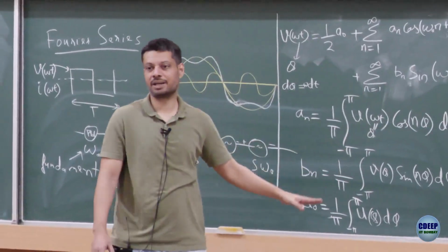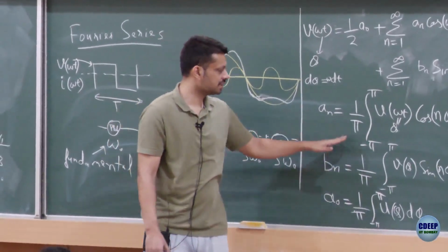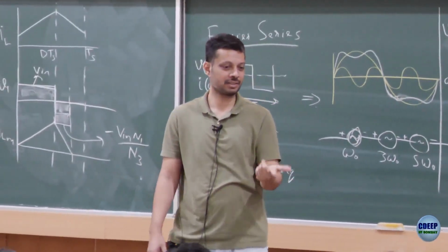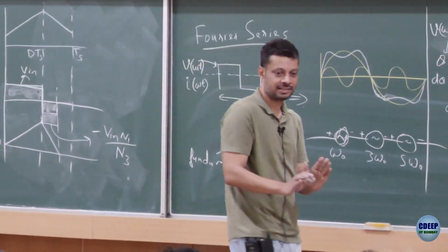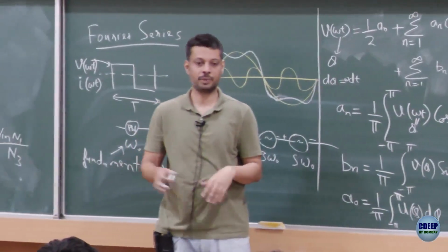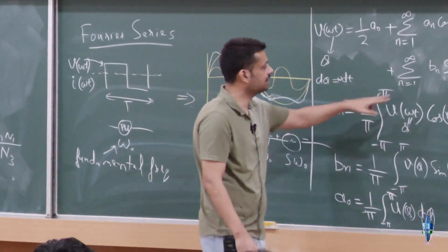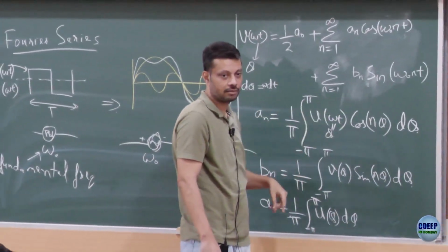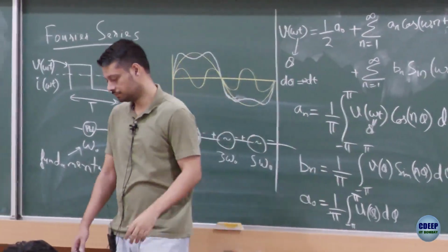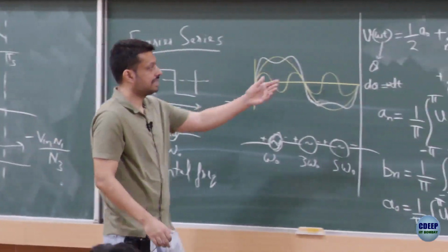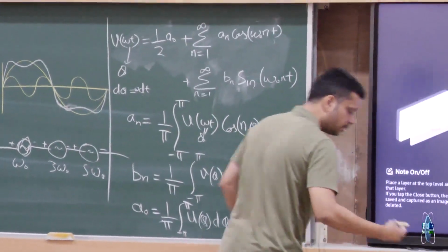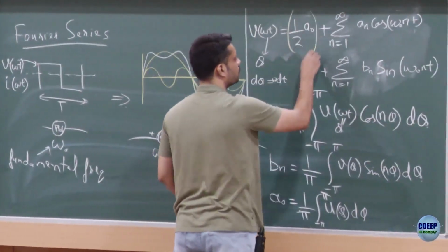That's the reason we are writing it down again, because I know there are different coefficients, there are different limits. The minus infinity to plus infinity you are talking about is the Fourier transform, not the Fourier series. For Fourier series we only talk about periodic signals, so we only integrate from either 0 to T or minus T by 2 to plus T by 2 or 0 to 2 pi. Oh, you mean n equal to minus infinity? Okay, fine. Sure. Fair enough. So the first term represents the DC component. If there are no DC components, this term will be equal to 0.